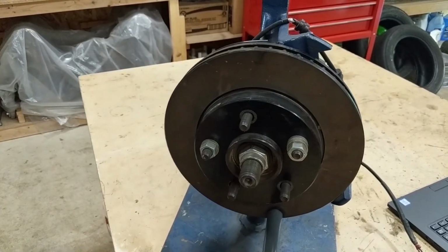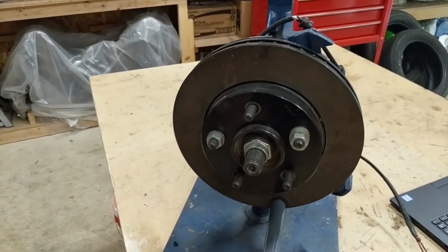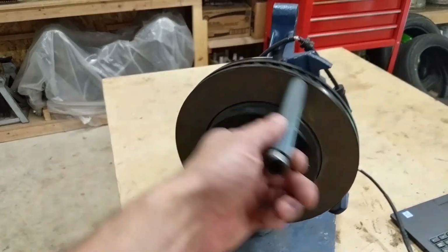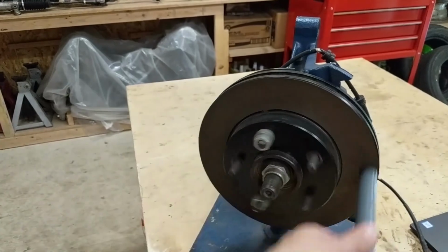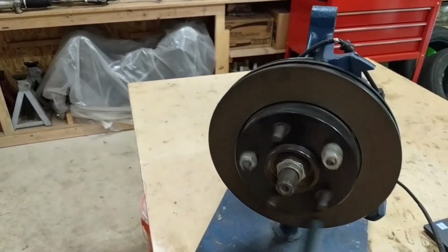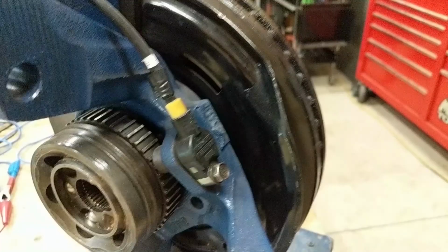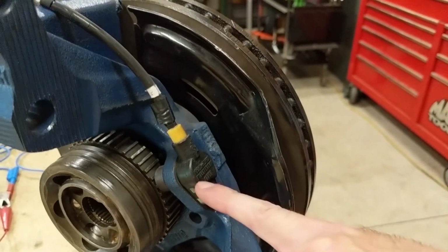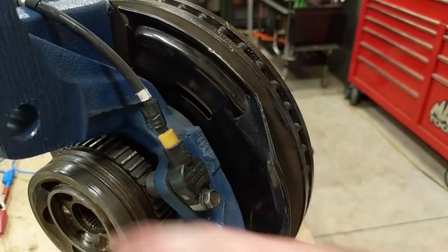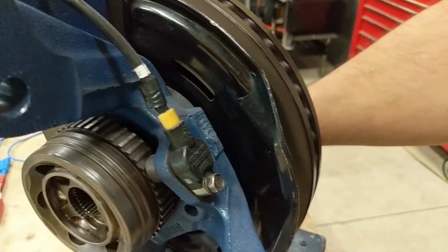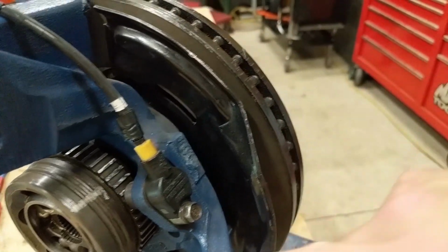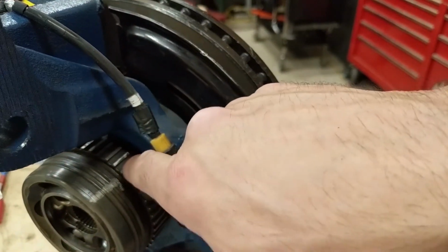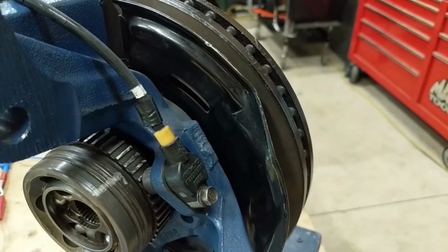This is an example of an AC generator two-wire wheel speed sensor. With this handle, I can rotate the wheel hub bearing assembly. And on the back side of the spindle, we have this toothed ring. This one has actually been damaged intentionally right here. One of these teeth has been ground down, so it's not the same square profile.